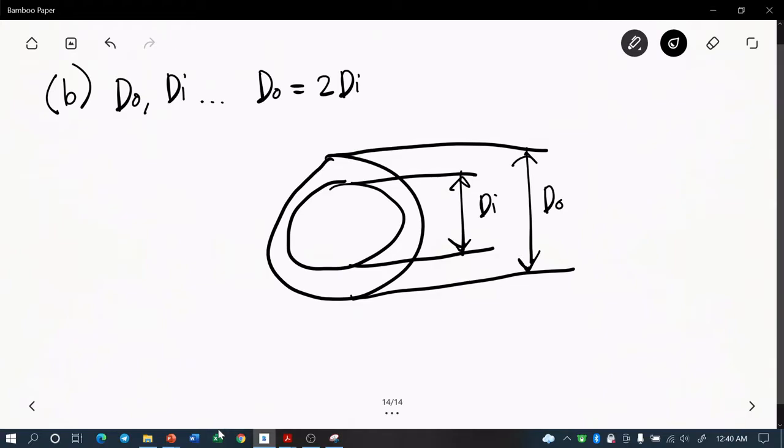Okay, so essentially the steps in solving the second requirement are the same as the first requirement, only that there are two sizes for the hollow shaft, and these are d sub I and d sub O. So since there are these two dimensions, the expression for the central polar moment of inertia is different from the solid shaft.